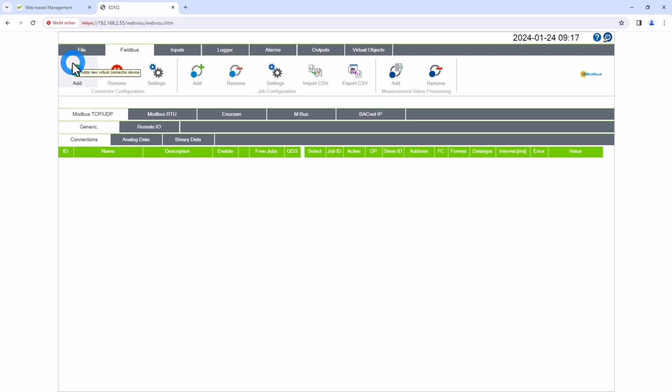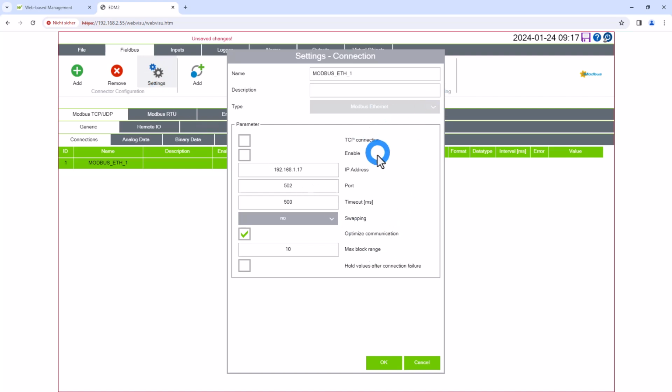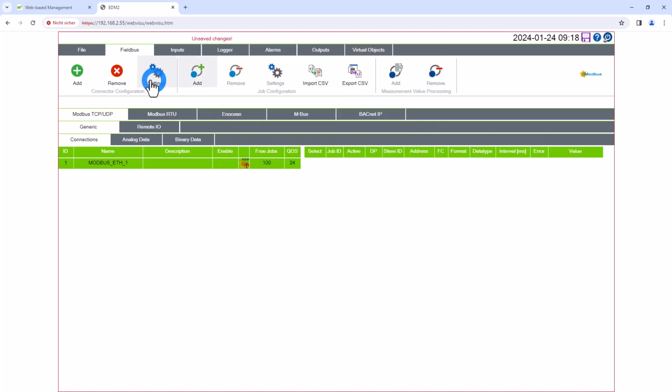So you add a channel. I can show you as a sample. Click on this channel settings and you can configure a TCP or UDP connection to a specific device with an IP address, port number, and so on. Usually, as you know it, Modbus TCP and UDP. I want to skip it because I have here one Modbus TCP device, but this is a WAGO controller.